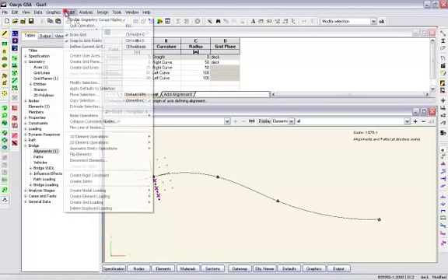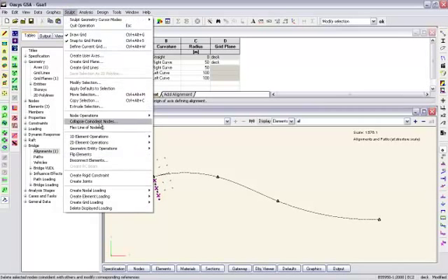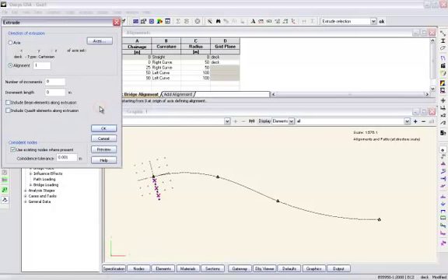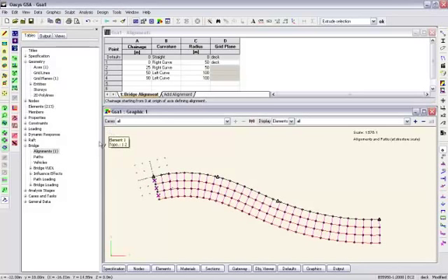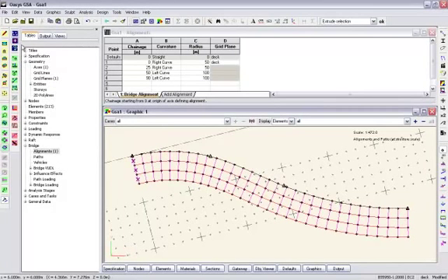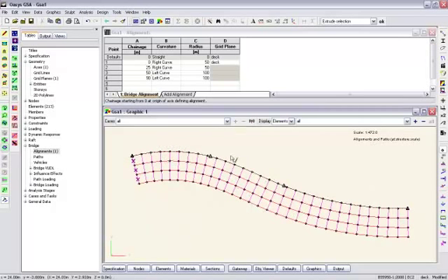this bridge grillage. So under the sculpt, I've got an extrude selection. Now, extrude is one of those wonderfully useful commands, and especially when we're doing bridges, because it can pick up alignments. If I say, well, 90 meters long, so 30 increments at 3 meters, and include beams along, and lo and behold, we have, let me switch that grid off, the bridge defined.